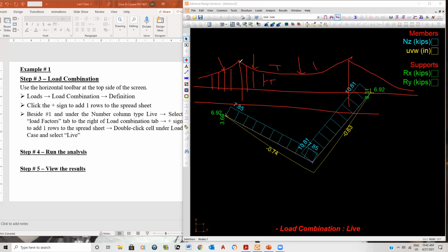And then what they used to do is make big masonry towers. If you look at the Brooklyn Bridge, they would make these either out of masonry or out of concrete, and concrete loves to be in compression. So you're using the right material for how it's going to be subjected to the forces: concrete loves compression, and you're using steel in tension, and steel loves to be in tension. So that was one of the big advantages of suspended bridges, that it really used the materials in the right direction.